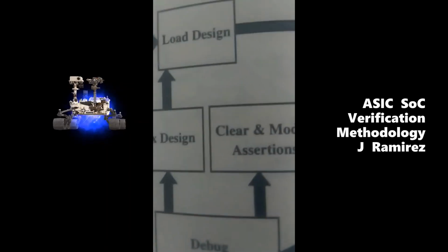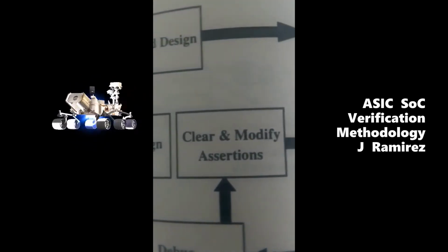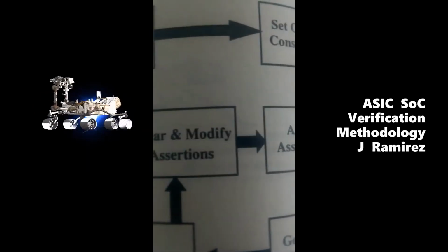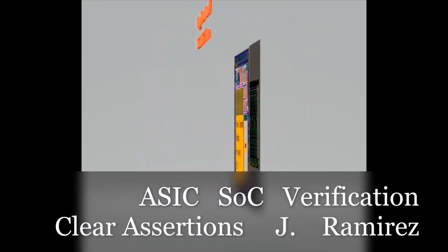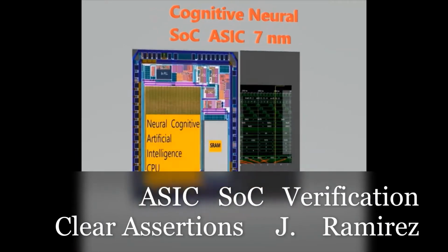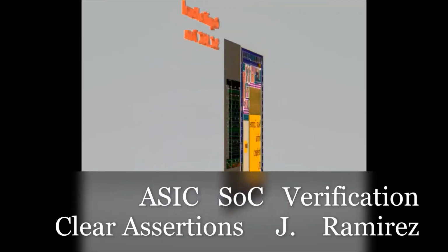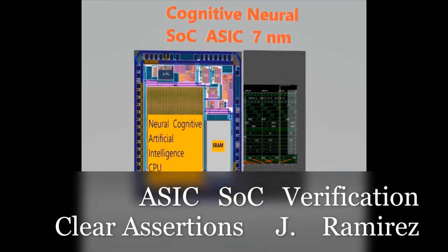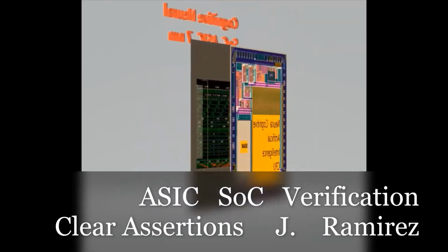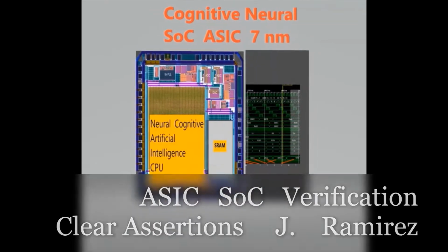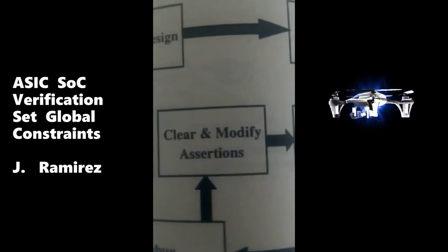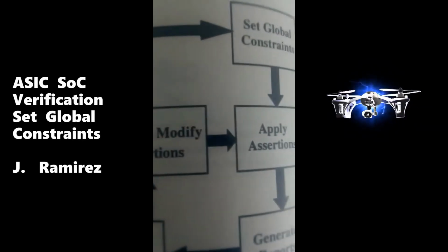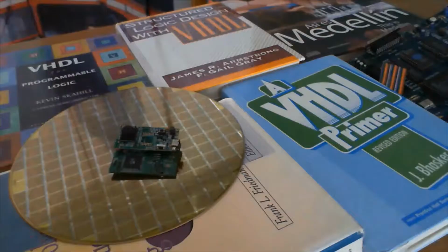As an example, a regular structure such as an adder may be very easy to envision and to lay out, since there is a high degree of parallelism among all of the bits of the adder. But the same adder when synthesized may not have this level of parallelism. Each bit can be constructed differently. This places some limits on the ability to do custom layout of synthesized logic.